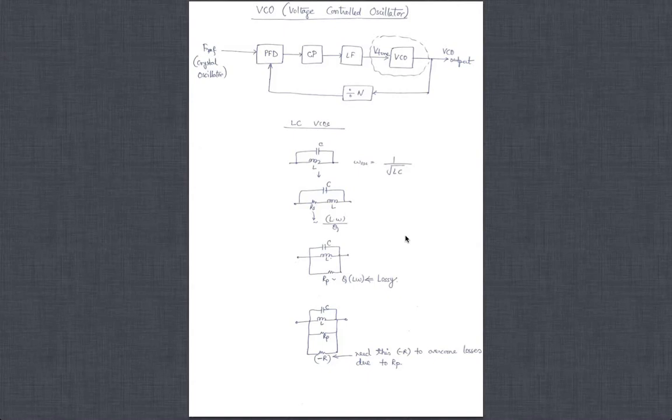As we have seen in the previous lectures on the receiver architecture, you're trying to receive at certain frequencies. So at the mixer you have to generate certain frequencies, which we call LO, for local oscillator. So how do we generate it? They are generated on chip from blocks called frequency synthesizers, and a key part of that is the VCO. So we'll try to focus on that in the next few pages that I go through.